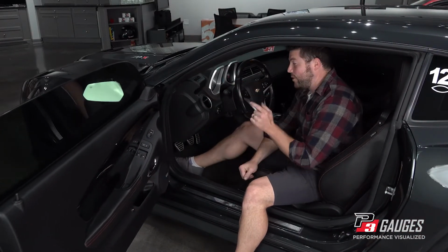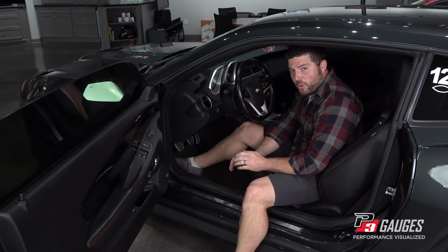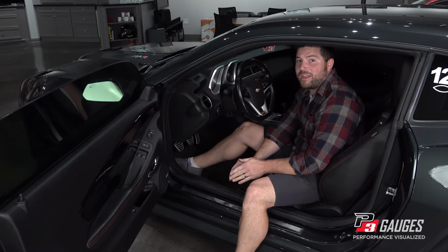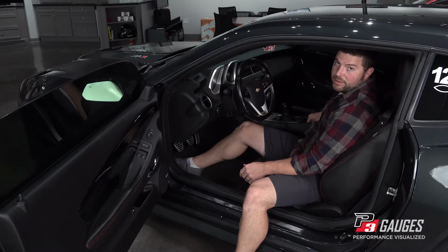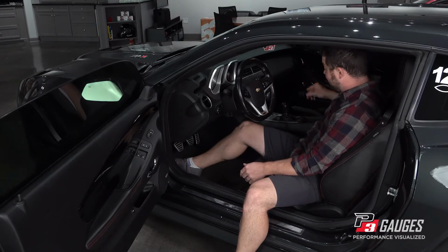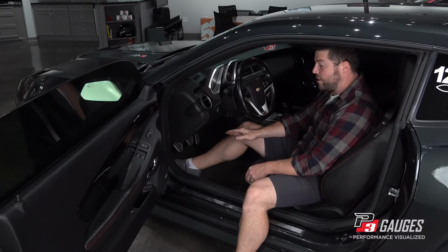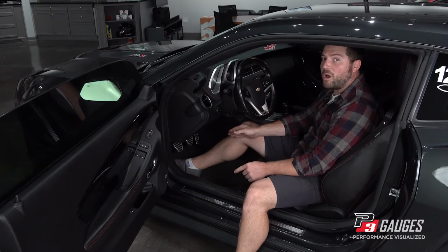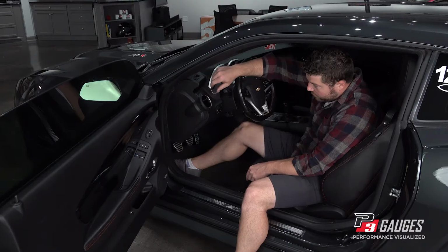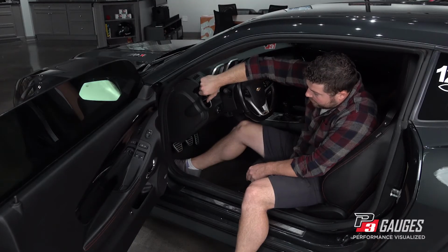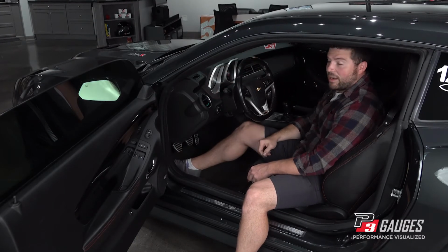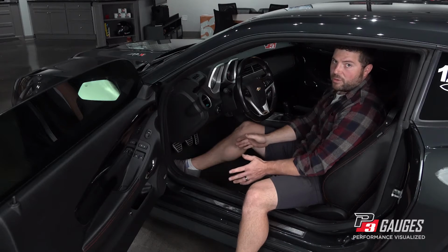One thing to note is that when you're accessing the config menu in your gauge, you don't have to have your engine running and you don't even have to have the ignition turned on. I've got my keys right here in the cup holder, not even in the ignition, and I have constant power at the OBD2 port. So as long as you've got your gauge plugged into the OBD2 port or hardwired to a constant power source, you can just hold both buttons until CONF pops up and then release. And now we're in config menu even without the engine running.